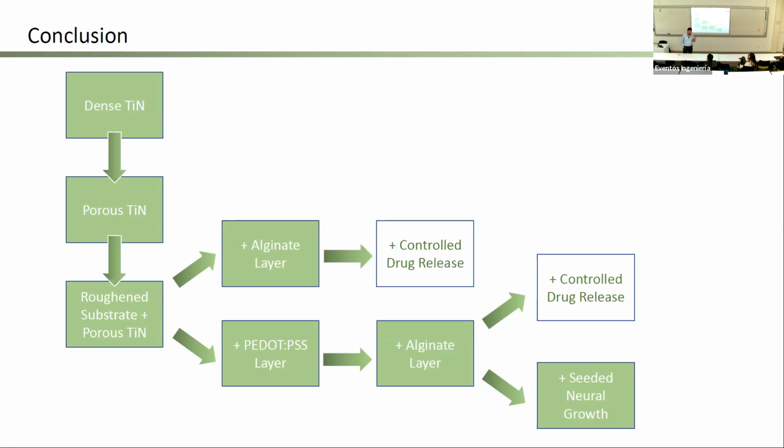For the tribological testing that we do, the contact stresses that we use are typically much higher than the reality. They are higher in order to enable us to shorten the test, but we limit how high they are, so as not to induce any plastic deformation, because then we start changing the mechanisms of damage.